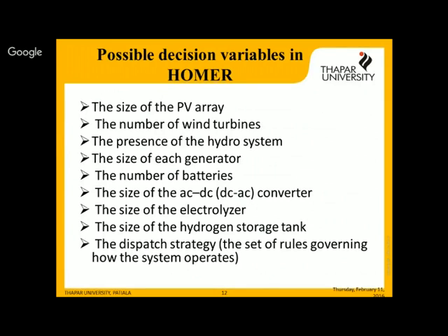Suppose you design a system for 20 years, let's say. The lifetime of the system is 20 years, right? Solar photovoltaic panels have a life of 20 years. Agree? What about the battery life? 3 to 4 years. So how are we going to accommodate that, that every 4 or 5 years we are going to replace the battery?